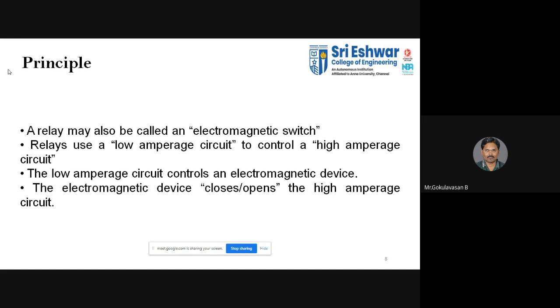It closes means automatically there is no fault in the circuit. That is the actual meaning. And the entire supply goes into the electrical device and it gets operated. Whenever there is a fault, there is a need to provide mechanical and electrical isolation between these parts, then automatically my trip coil or relay should get opened. Then only the tripping operation will take place.